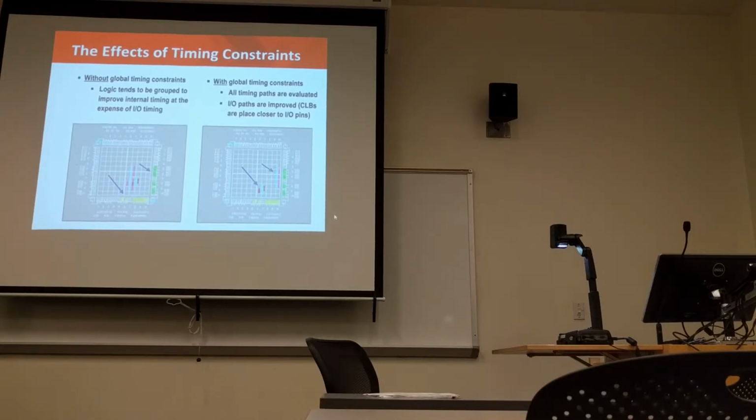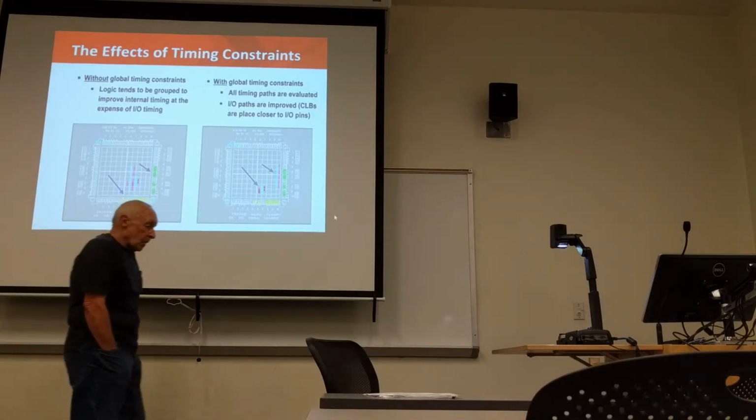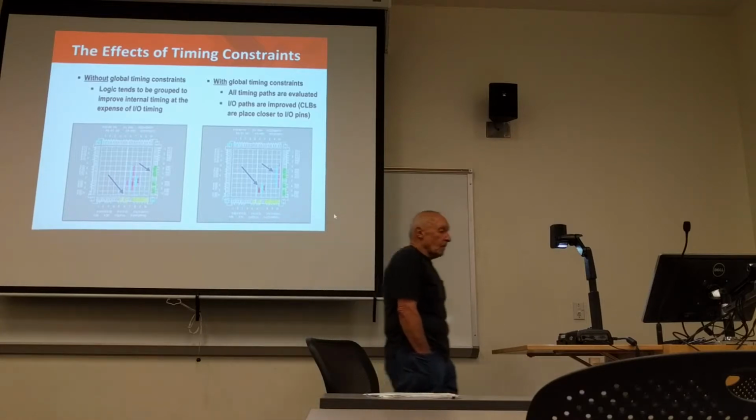Note that the tools do not anticipate any ground balance problems. The tools do not know when the signals will be toggled or how many signals may change simultaneously. It is left to the designer to be certain that you try to disperse switching outputs that are switching simultaneously to help avoid any problems with ground balance. To help with that, the Architecture Wizard and PinAhead recorded learning module discuss how to place I/O pins efficiently so you reduce the risk of creating a ground balance problem.